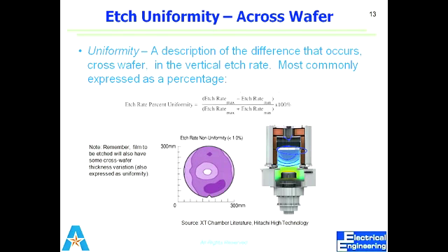You know this thing, when we were discussing the etchant, what should be the properties of an etchant while selecting whether this etchant is good or not. Out of many parameters, it should have a high etch rate, it should not be very dangerous, it should be readily available, there should be some way to dispose of that etchant, and all the other parameters.